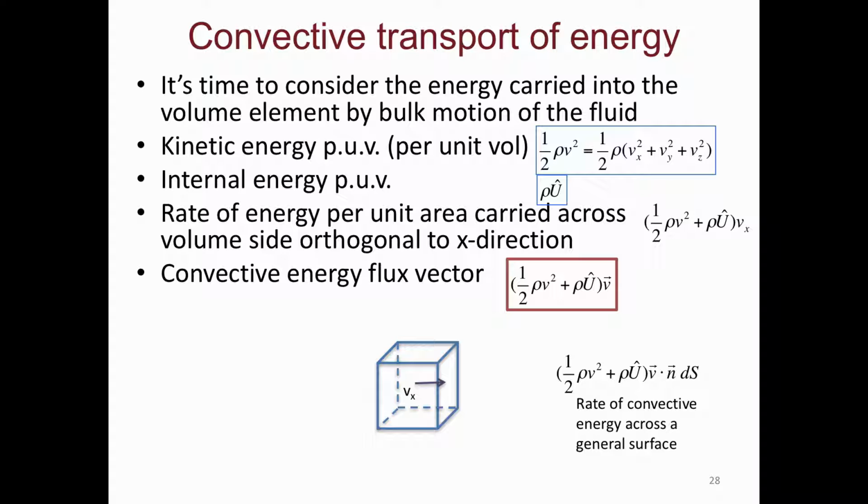Okay? It's a silly question, but how are you bringing internal energy into a system? So you can think about this square here, right? My coordinate system and my equations are tied to the coordinate system that is static. But my volume is literally walking by. So as I'm walking in, I'm bringing my energy.